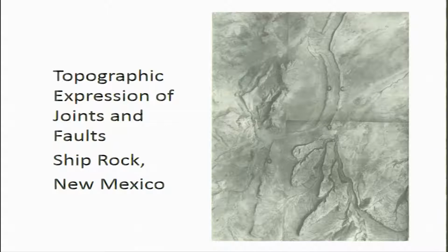Okay, so these expressions show the faulted and jointed terrain. Okay, don't go on this line, because these lines are showing the mosaic of this photograph. So here you can see that a fold is coming like this, which is delimited here and ends up here. Okay, and this feature is very prominent on this image.